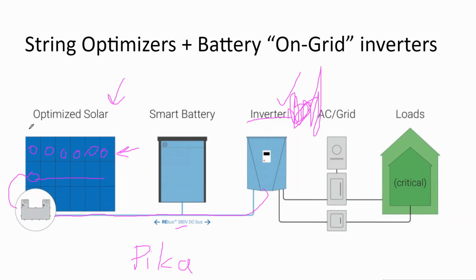And they say, okay, well, we're not going to have 10 or 11 panels per circuit. We're going to string up enough panels to get us to about 380 volts. And so they're really taking the operating voltage of the panel, which might be between 360 and 400 volts, and just keeping it at 380.